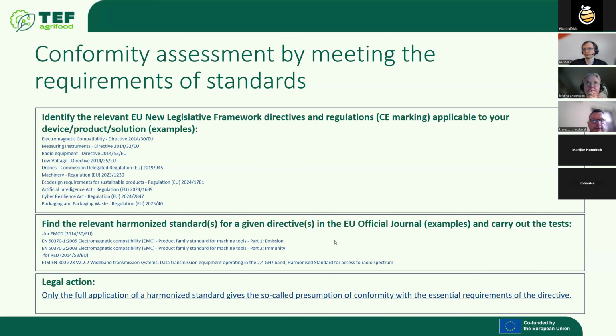Please keep in mind that the Radio Equipment Directive also covers EMC, electromagnetic compatibility, as essential requirements, and the most important is effective use of spectrum, as well as electrical safety. And there are some new essential requirements related to cybersecurity. So in the list of standards, we may also find harmonized standards that are related to cybersecurity.